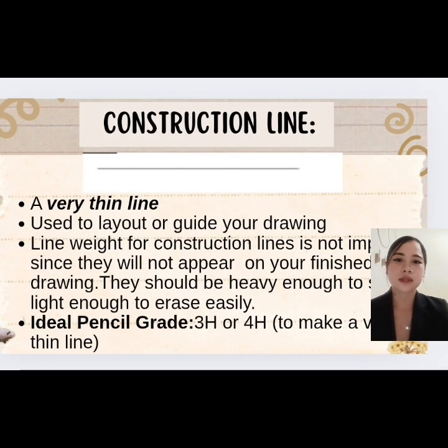So let's proceed to the second line, the construction line. A construction line is a very thin and light line used as a guide when creating a technical drawing. It helps you lay out the basic shapes, proportions, and alignments before drawing the final lines.